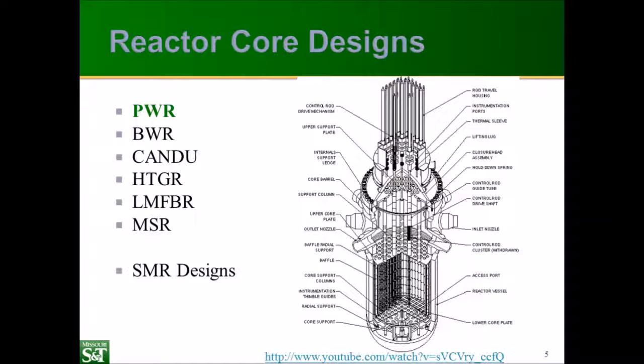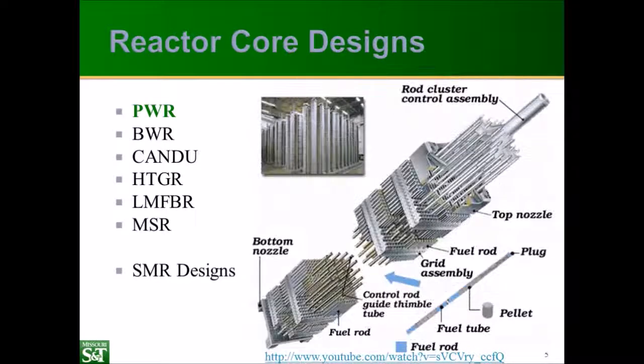Now, inside the pressure vessel, where the core is, mostly we're talking about convection from the fuel to the coolant. And here, power control is usually used by boron shims, chemical shims, rather than control rods for a PWR. Finally, if we get all the way down to the individual fuel bundles, here we're going to have heat generation in the fuel due to the fission chain reaction. And once that heat is generated, it has to conduct through the fuel and the cladding. And once it reaches the outside of the cladding, it's removed by convection or boiling in the core.